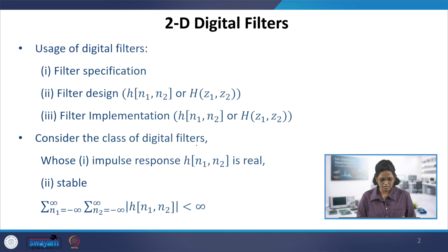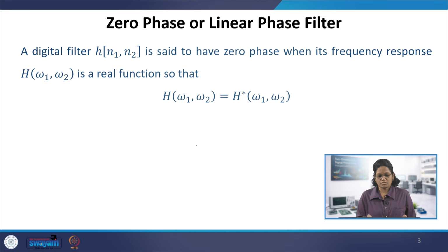So these two requirements we have for the discussion, so that practical filters can be designed based on that. Taking the FIR filter which is linear phase, we had seen the midpoint symmetric and midpoint antisymmetric cases of type 1, type 2, type 3 and type 4 filters, and how the coefficients are spread in the impulse response. Actually h of n has coefficients that are midpoint symmetric or midpoint antisymmetric, and the length of the coefficients depends on that. We did this for 4 types of filters. That offers the linear phase characteristics of the FIR filter.